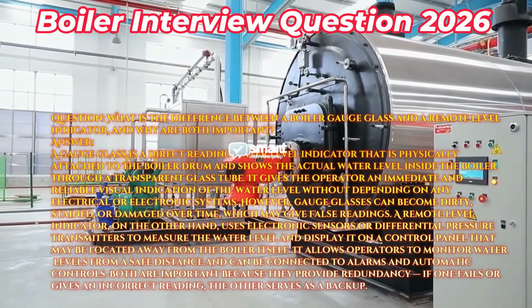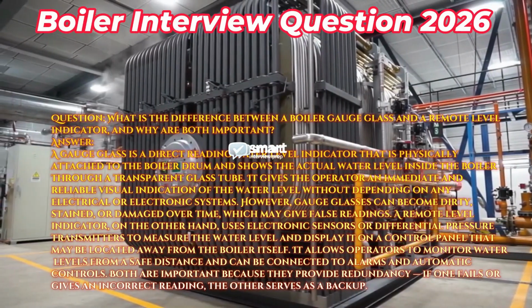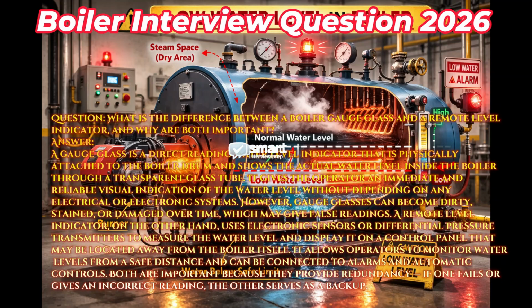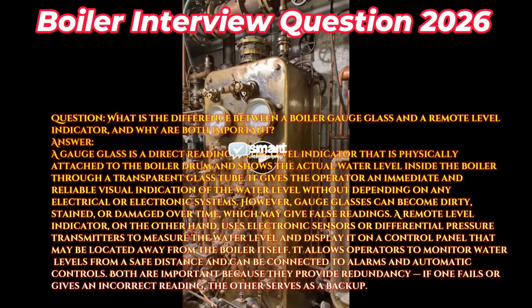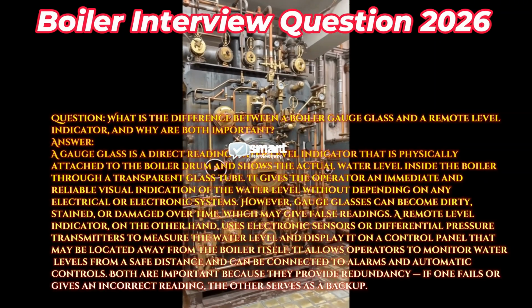It gives the operator an immediate and reliable visual indication of the water level, without depending on any electrical or electronic systems. However, gauge glasses can become dirty, stained, or damaged over time, which may give false readings. A remote level indicator, on the other hand, uses electronic sensors or differential pressure transmitters to measure the water level and display it on a control panel that may be located away from the boiler itself. It allows operators to monitor water levels from a safe distance and can be connected to alarms and automatic controls.